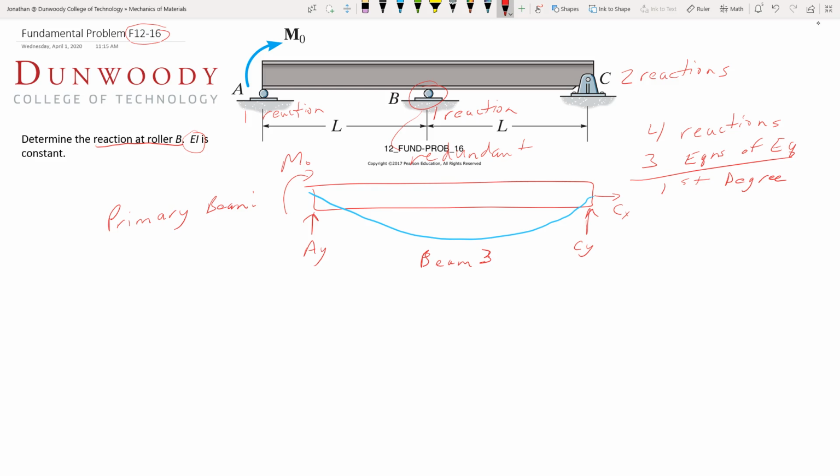our deflection here is V. It's going to be negative M0x over 6EIL. And L in the diagram is the whole thing. And that is going to be multiplied by L squared minus x squared, where we care about what position we're at. So that's what we've got. We've got essentially the mirror of that, but we can use that same equation.